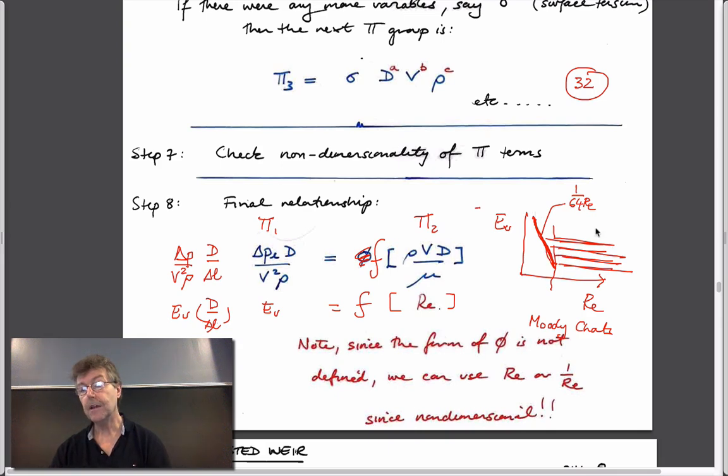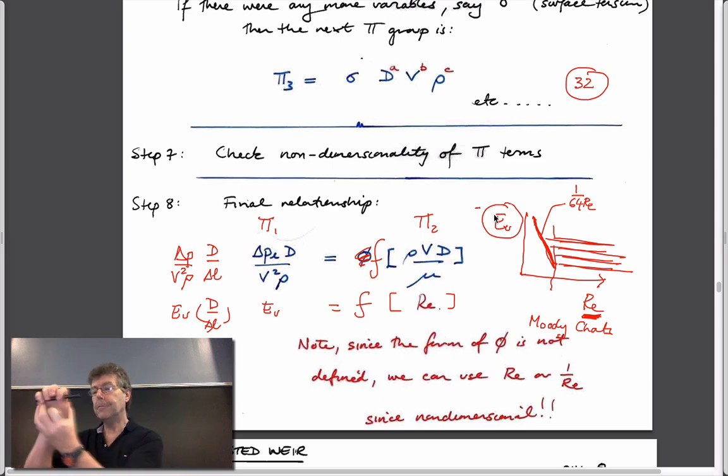We get a single relationship, but when we deal with non-laminar flow, then it breaks down and we have multiple relationships. But nonetheless, we're guided by the fact that it's Reynolds number which indexes the flow regime, and Euler number, which says something about either the force that's applied on a structure on the outside, or the force that's applied on the inside of a structure, on the inside of a pipe. And of course, we don't really care about what's inside the pipe. We don't really think of it as being the force you have to apply to be able to keep that pipe static because it's being flowed along. We think of it more in terms of the pressure drop you get in the pipe that you have to overcome with a pump to be able to do it.